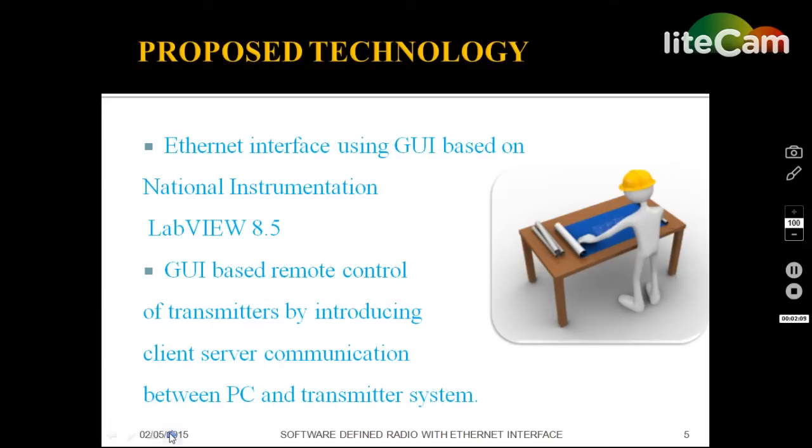Ethernet interface uses TCP communication protocol, and the Raspberry Pi sends the parameters and a message to the transmitter section through USB port. Serial port in the PIC transmitter node receives the data and transmits a message in adjusted frequency and power level. Receiver part operated with the corresponding transmitter frequency will receive the data. Power level can be verified by measuring the range of transmitter and receiver. The higher the power level, the greater the range will be.